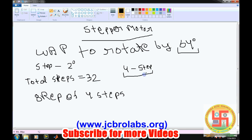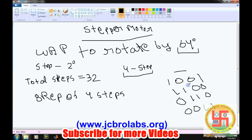Now we have a 4-step sequence. That means these 4 commands which we just saw, 1001, 1100, 0110 and 0011, are the 4-step sequence, and this sequence makes a complete set. So further divide this 32 by 4, and we'll need 8 times of this. We need to repeat these 4 steps 8 times. If we write this program, then our motor will be rotated by 64 degree.